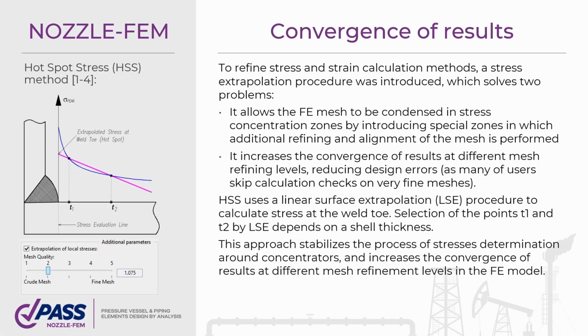1.05. The program implements the so-called hot spot stress method with extrapolation of stresses, which allows getting more accurate results with a raw mesh and reducing the additional safety factor.